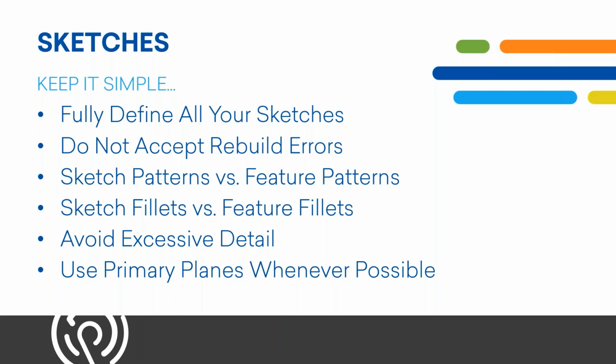The reason is going to be explained a couple different times, but features are things that you can suppress. Features are things that you could minimize or make simple for alternate configurations. That's going to come into play because when you're working with a large assembly, you might want all the detail at some point in time. Maybe you're going to manufacture a part, but do you need all the detail all the time?